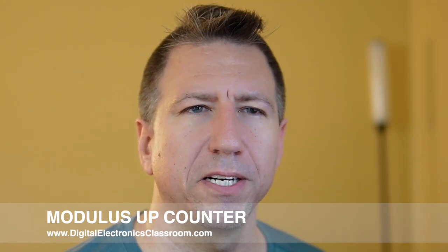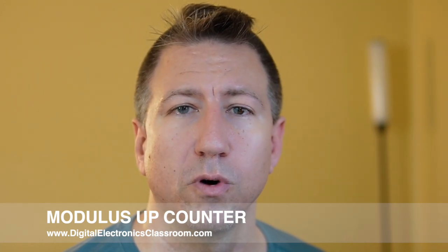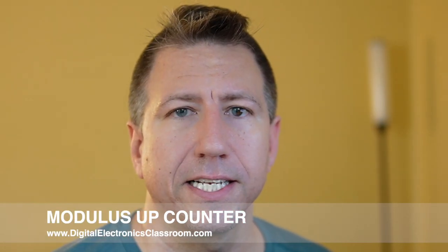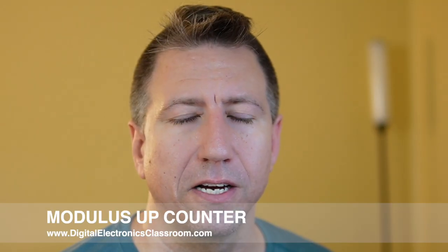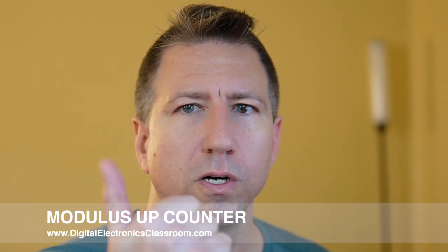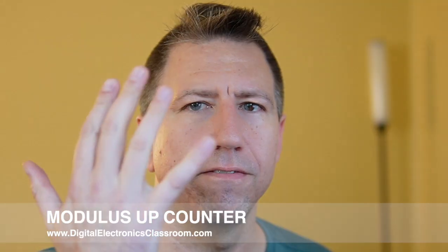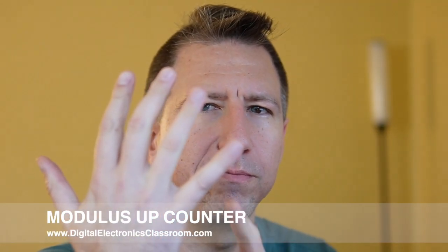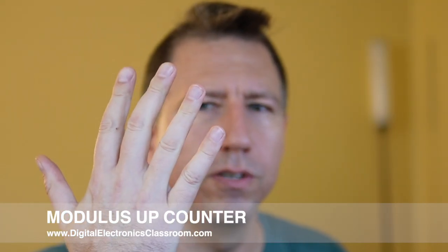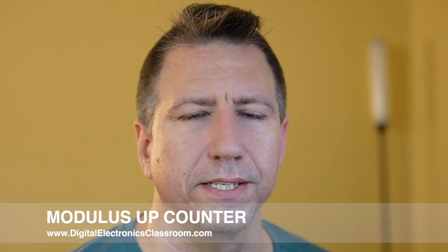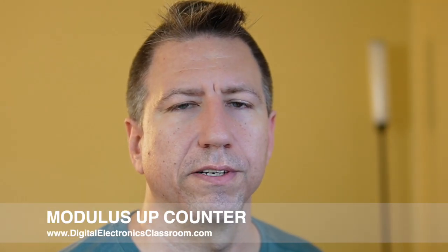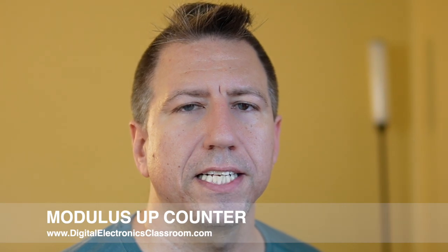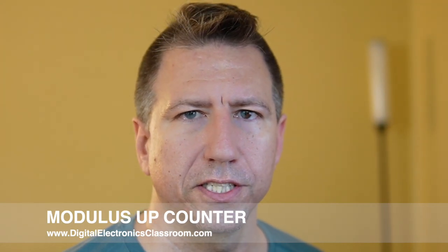And so one range that we might want to count to is maybe 1 through 5. Maybe we start at 1 and count up to 5. In that case, we would have a mod 5 counter because our states would be 1, 2, 3, 4, 5. Now, it's not mod 5 because the last number is 5, it's mod 5 because there's 5 states. So it would still be a mod 5 counter if we were counting from 2 to 6, or from 3 to 7, or 4 to 8, and so on. So the number of states that you count through is the modulus number.